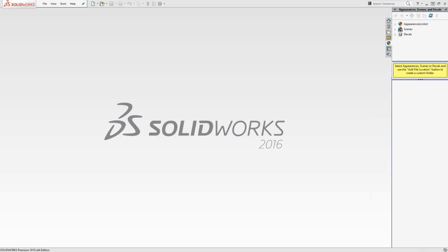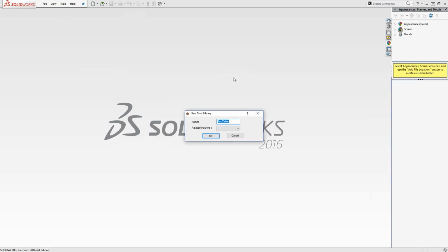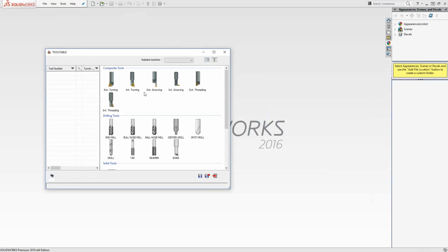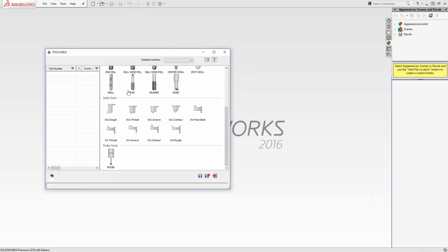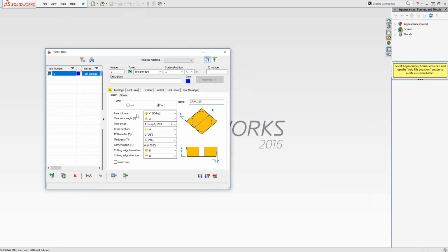This is basically going to be a review of turning tools, and then I'll show you how to actually create a custom turning tool. So let's do a little bit of a review. When you create turning tools, you go to SolidCAM Tool Library, Create Tool Library, and let's say we create a turning library. If I click on Add Turning Tool, we have composite tools and we have solid tools. For the standard tools you would see in your everyday turning operations, you're probably going to use composite tool. You can define your inserts using standard nomenclature, just pull it from the pull-down menus.